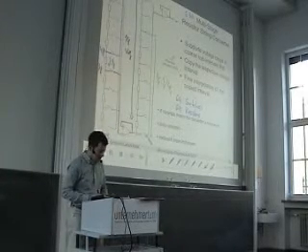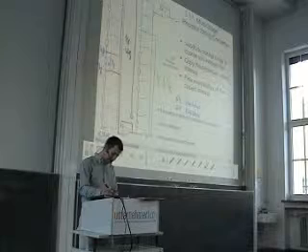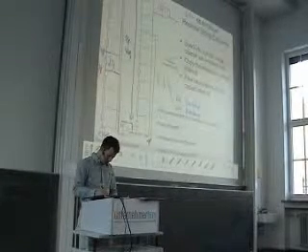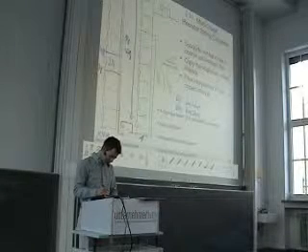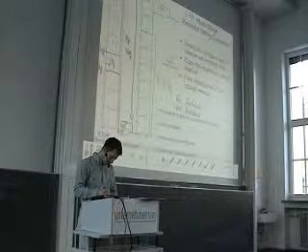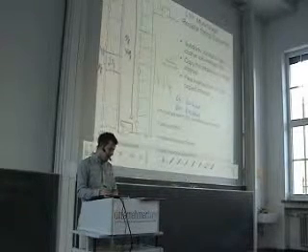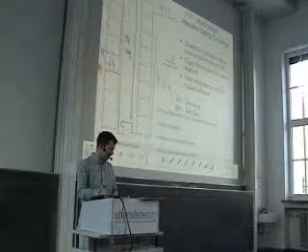So question is, what is the complete output voltage? The complete output voltage is this voltage drop here. And then we go over this buffer and we see here, okay, there is another 3/8 times Vref.